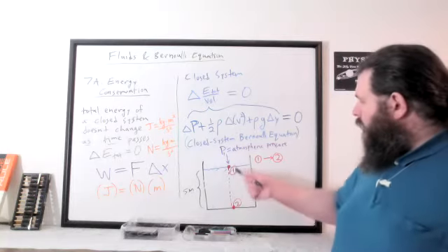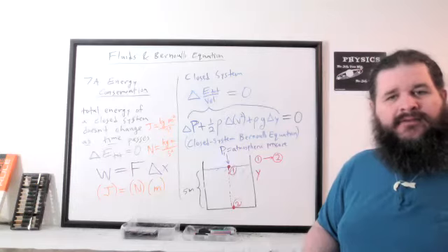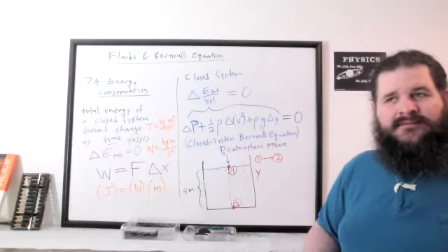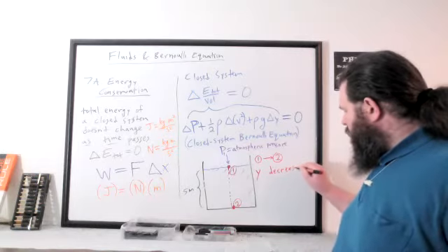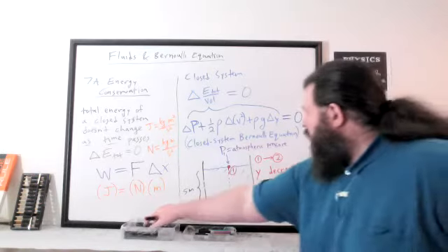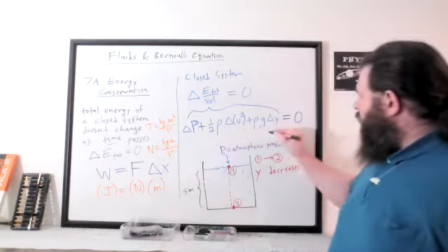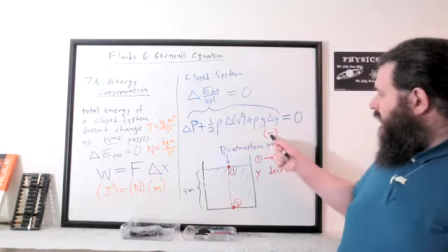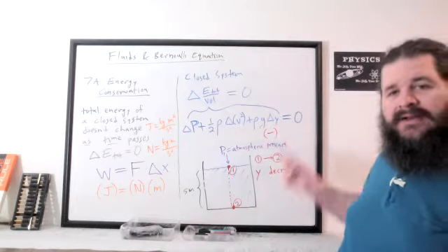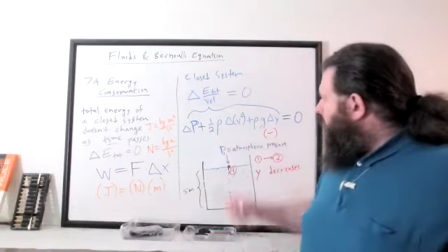Yeah, the height. Y is changing, specifically as you go from 1 to 2, being consistent about our direction here. From 1 to 2, what's happening to the height? Right, height is decreasing. So going back to our Bernoulli equation, we can say that delta Y is a negative value from 1 to 2. And if this is a negative value, there's got to be some positive also to make sure they add up to 0. So one or the other of these, or at least both of them combined, has to be a positive value. What about speed?